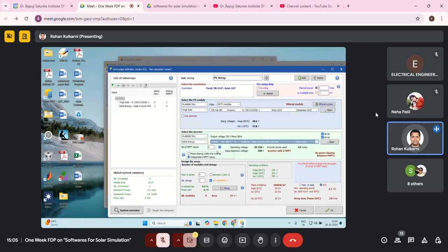In India, we have tested with the pyranometer what the input is, and sometimes in summertime we get more than 1000. It's easily available in India. So the saying is that if you are installing a 3 kilowatt plant and select a slightly higher inverter, it's okay. I'm selecting 4 kilowatt, it's not that much.